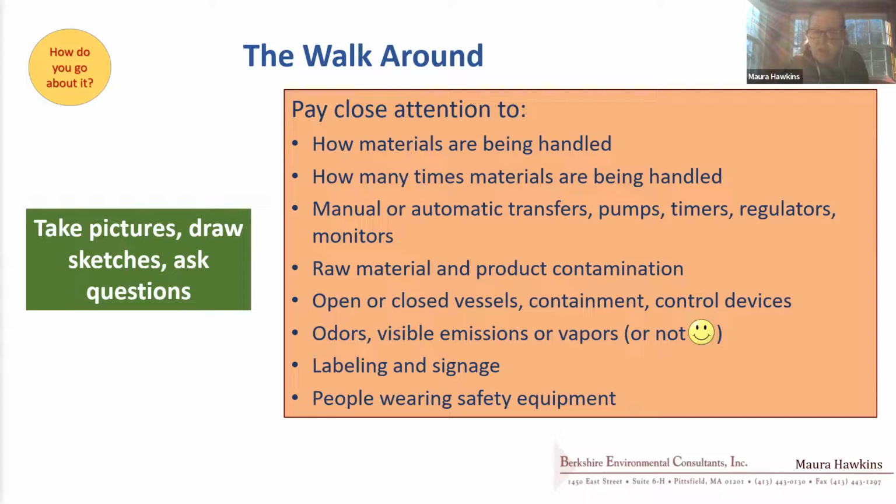And you're looking for people wearing safety equipment. I had a plant where people were always wearing masks in this one area. And I'm like, what are you guys doing that for? Oh, God, every time we open this thing, there's this big burst of powder that just goes blowing all over the place. I'm like, okay, well, that's an interesting thing. So you're looking for safety equipment. It tells you when people are wearing safety equipment that there's a risk there of some chemical being released or something happening to a product.